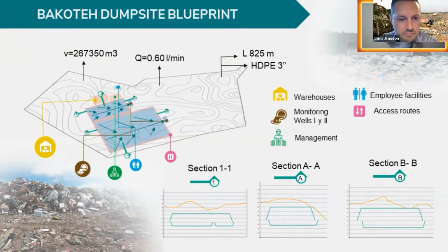The next point to talk about is the leachate drainage. It will be a recirculation in drains labeled to discharge. The volume of leachates is determined on the basis of the Swiss method. Also, we need to build monitoring wells to check the leachate generation. For management of gas, consider that it's necessary to install 4 burners. Considering a recommended distance between each one, we can see here where they will be placed.